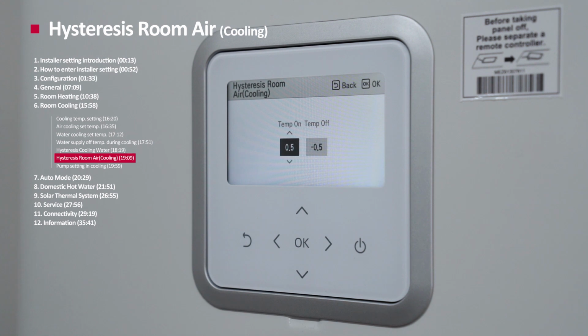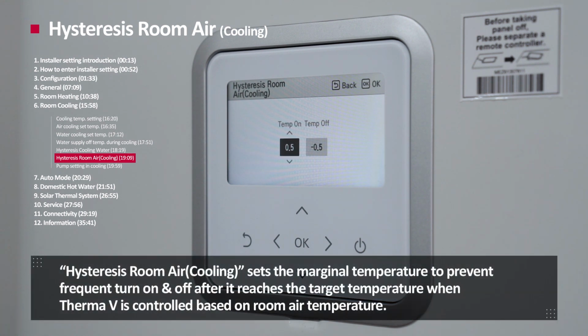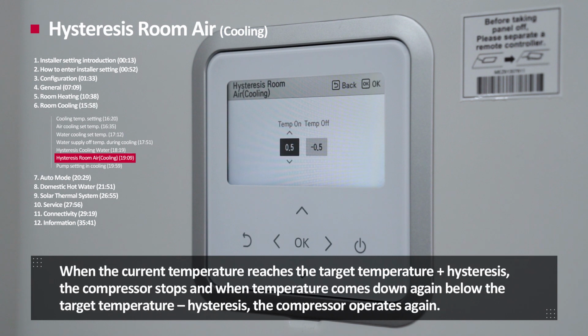Hysteresis room air cooling. Hysteresis room air cooling sets the marginal temperature to prevent frequent turn on and off after it reaches the target temperature when Therma V is controlled based on room air temperature. When the current temperature reaches the target temperature plus hysteresis, the compressor stops. And when temperature comes down again below the target temperature minus hysteresis, the compressor operates again.